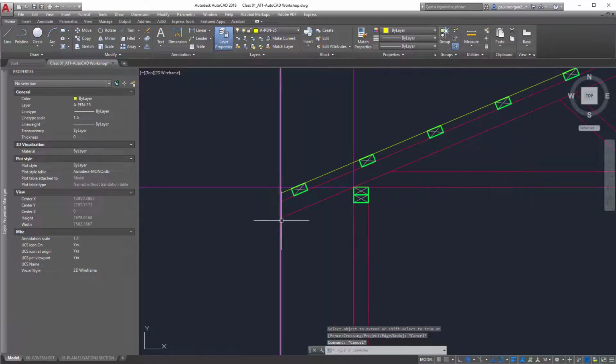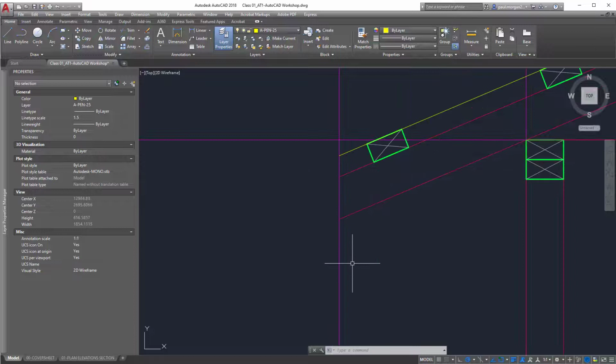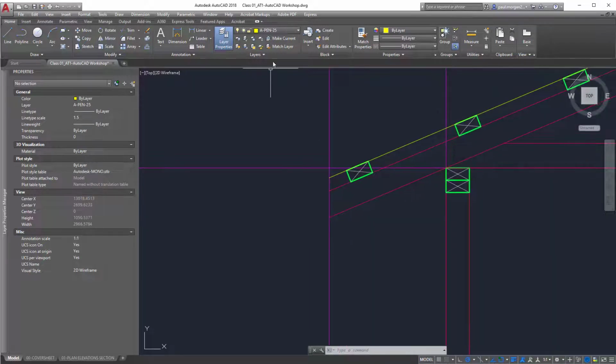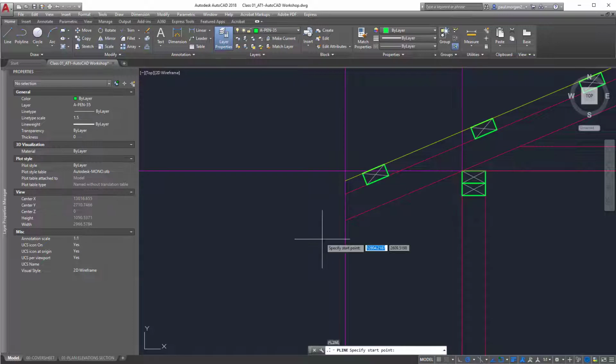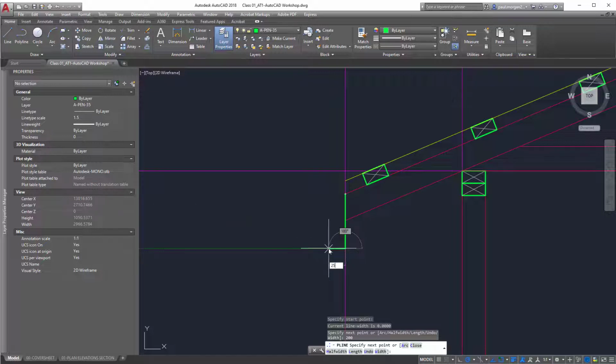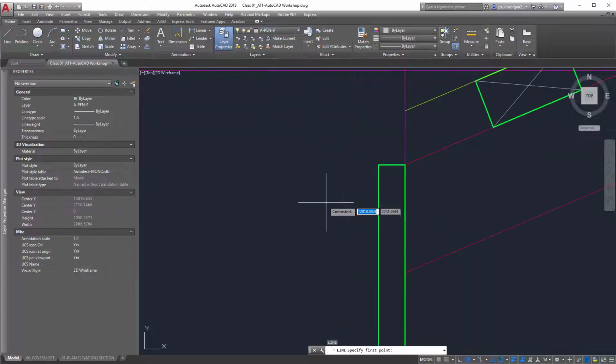All right, almost there. Next up, we're going to draw the fascia board, and the fascia board will go on the edge of the truss here, and I'm going to use the same line weights that we used to create the timber stud. So polyline, I'll start here, and I'm going to go down 200 mil and then across 25 mil, back up 200, done. And now I'll just do the crisscross with pen layer 9.